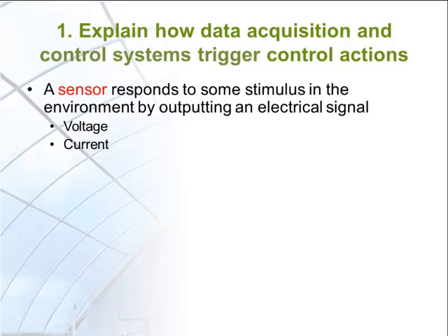Knowing that voltage drops over long cable lengths due to wire resistance, a voltage output transmitted over a long distance will have a large voltage drop as the transmission distance increases. Additionally, some voltage outputs of sensors are sensitive to the noise induced by nearby motors, conveyor belts, and radio transmissions.